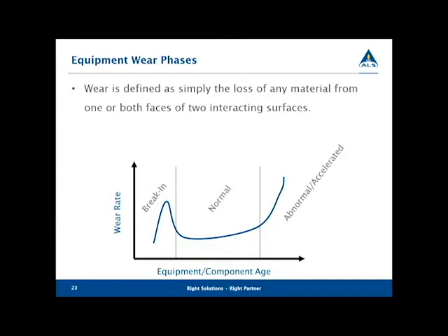The break-in phase typically is attributed to machining of a new component. A lot of times when you buy a brand new asset, it's not completely clean on the inside. The metal, for whatever reason, and there are several different reasons why, doesn't polish completely smooth, so there's a break-in phase to this. It isn't until that gets worn down somewhat that we actually see a reduction in that wear. If it's coming from internal sources, that's one thing; if it's coming from an external source, that's a different story altogether.